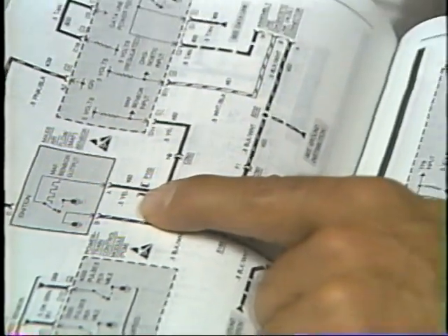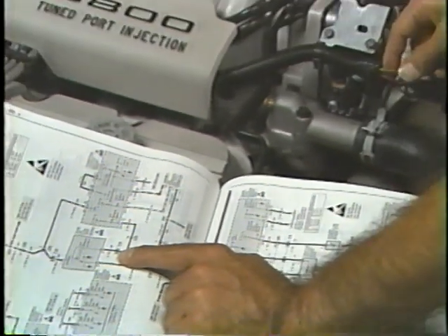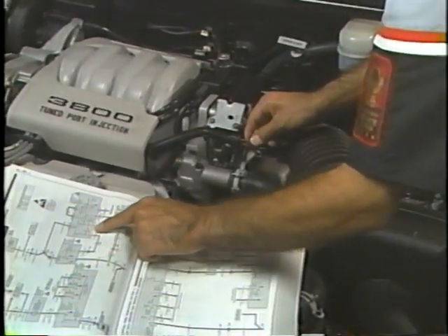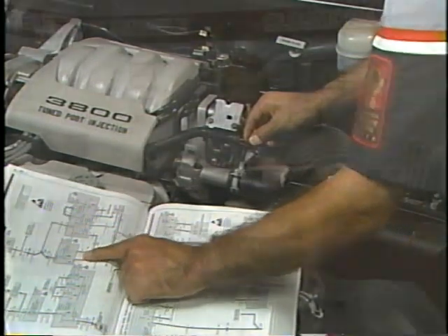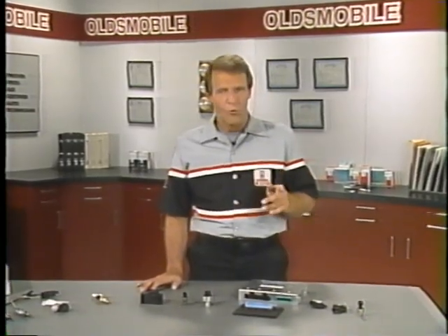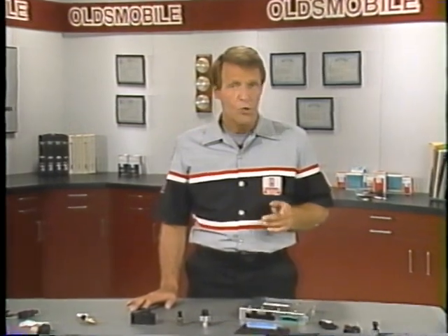As you're troubleshooting, use this basic information, along with the 6E or 8A schematic, to determine how the circuit should work. Keep in mind that these circuits need the correct voltage supply for the sensor, a good path to ground, and of course, a properly working sensor. Also, don't forget the PCM itself must have a good voltage supply and ground. If you're seeing symptoms that seem to involve more than one sensor, be sure to check PCM power and ground. Then, using nothing more than a scan tool and a digital multimeter, you'll be fixing them right the first time.